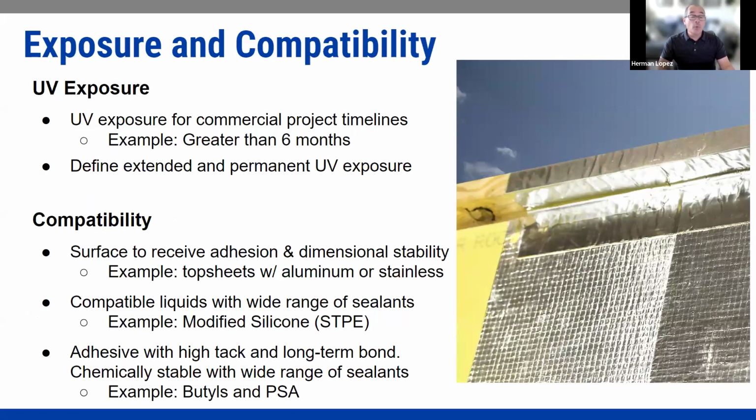But UV exposure. When we talk about UV exposure, we're really talking about two different types: constructible UV exposure, as far as the amount of time it can be left exposed to UV, and extended UV, open joint systems, if you will. Talk to your manufacturers. Certainly the best is 6 months and greater. It doesn't take much. I just spoke to somebody in New York who said that they went 11 months with their product exposed to UV before they were able to cover it up because of some issues with the structure. So as you specify your products, make sure that you're looking at the UV exposure.